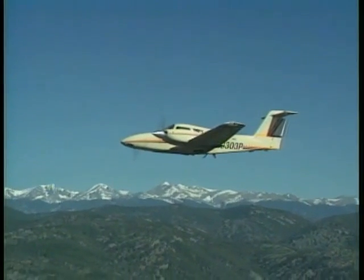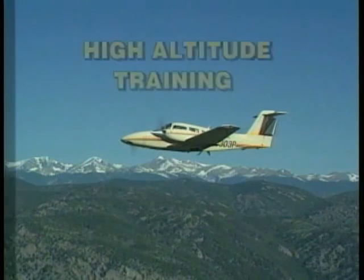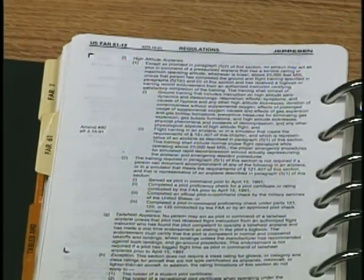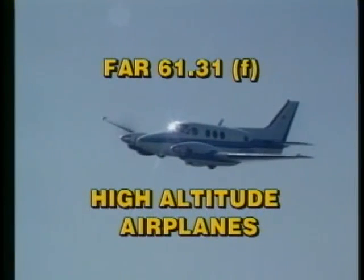Becoming proficient in high-performance single-engine and multi-engine airplanes also allows a pilot to operate at increasingly higher altitudes. Training in high-altitude flight is another opportunity for providing specialized instructional services. FAR 61.31 requires specific ground and flight training for a pilot to act as PIC of a pressurized airplane that has a service ceiling or maximum operating altitude, whichever is lower, above 25,000 feet MSL.